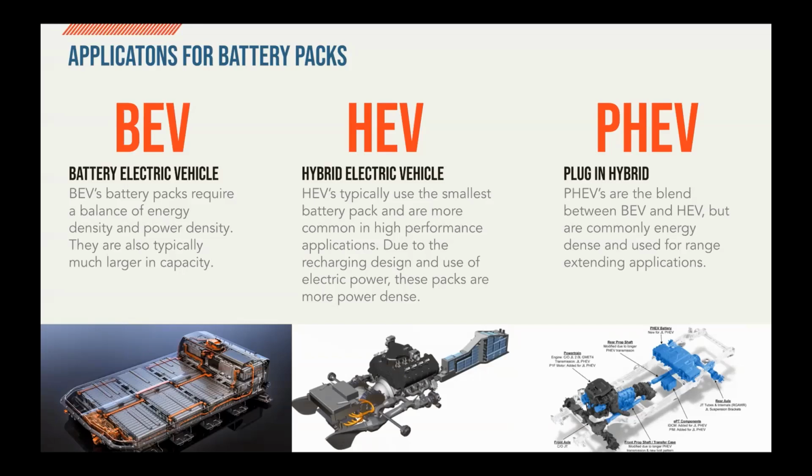Hybrid electric vehicles usually have the smallest battery pack in form factor and are much more going to be designed around power density, because the only way that they recharge is through the vehicle's primary powertrain system or combustion engine. They rely on regenerative energy through braking and other systems on the vehicle to regenerate while the vehicle is in motion, and then provide power for accelerating or hybrid power to extend range.